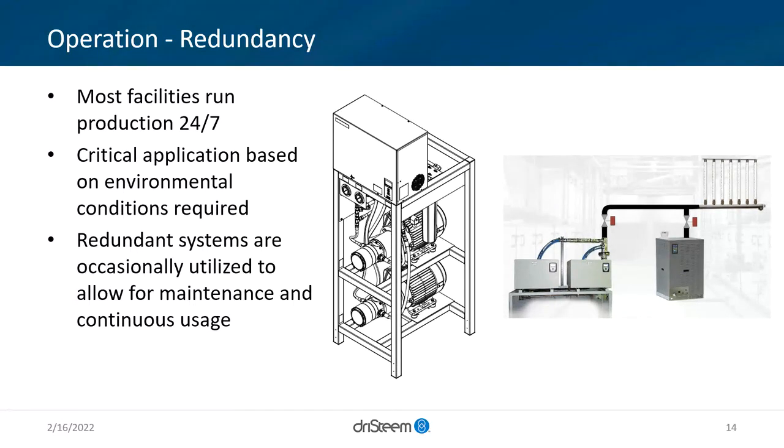So I talked about the example of a high pressure atomization for a bulk majority of the load, and then a trim humidifier for that tight control with a resistive unit. This is 2 isothermal, where the GTS, gas to steam, will give the high load, and then really that tweaking of that load would be by the electric resistive.